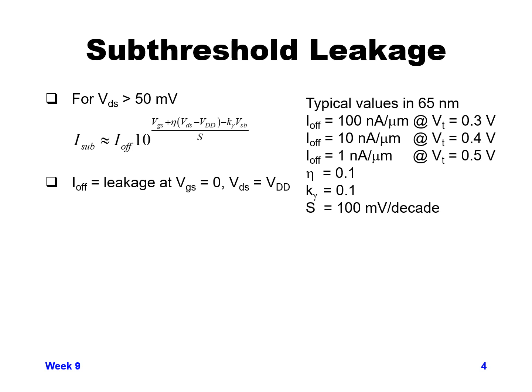So in effect, a 100 millivolt change in your threshold will give you one decade, or a factor of 10 difference, in your off current. Changing your threshold voltage by a small amount can have a very large logarithmic type effect on your leakage.